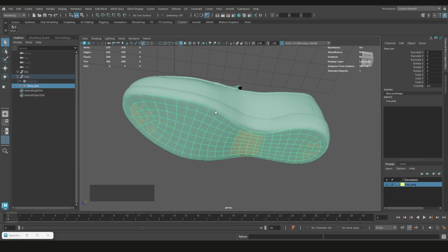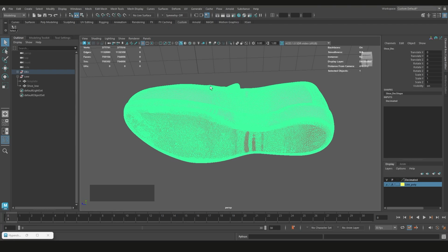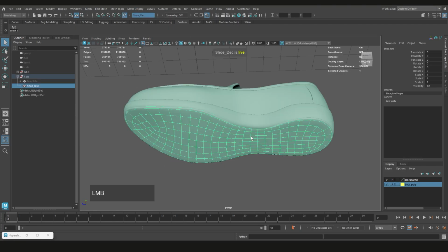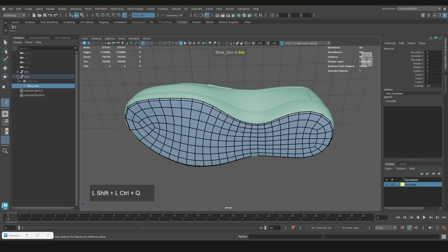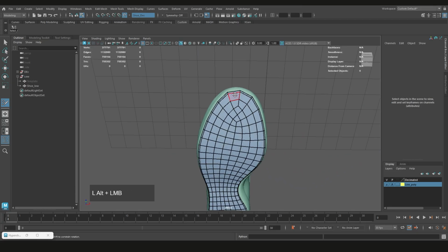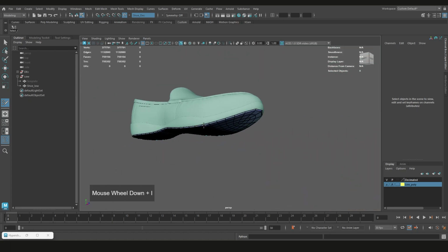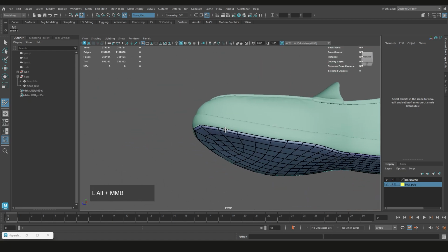So it'll pretty much be flush on there, okay? And what I want to do is go back to this piece and say make live object, and then on this piece I'll press Control Shift Q, and now this will be the layer that we use to retopologize, right? So basically I'm using what we had, and I'm just manually retopologizing.